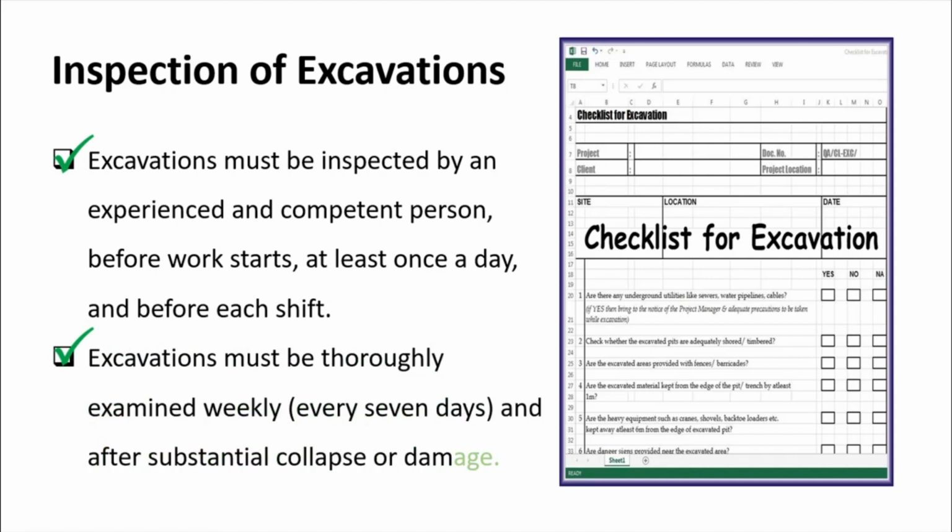Excavations must be thoroughly examined weekly, every 7 days, and after substantial collapse or damage. They should be thoroughly examined by a competent person like a structural engineer, so that he can see if the excavation is still safe for the works to be performed inside it.